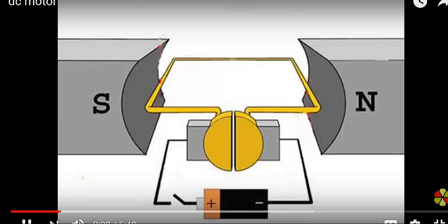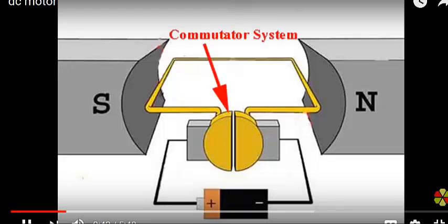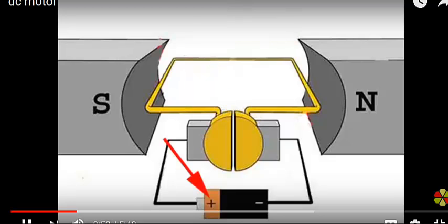So you've got the magnetic field, and right now the loop is parallel to the commutator, as it's called, not a communist. So there he's pointing at the battery. He's closed the switch. The current flows through the wire.